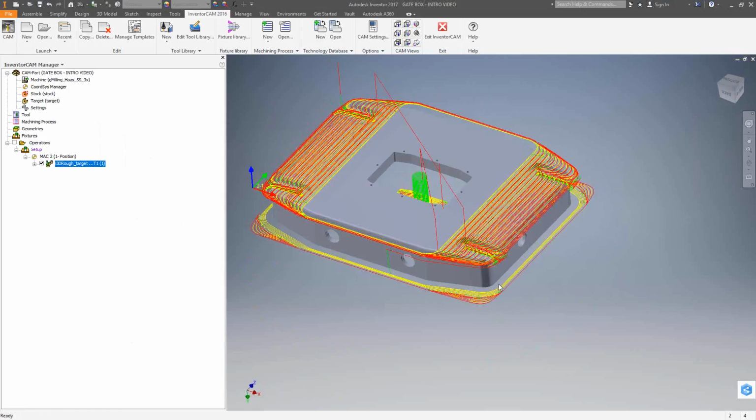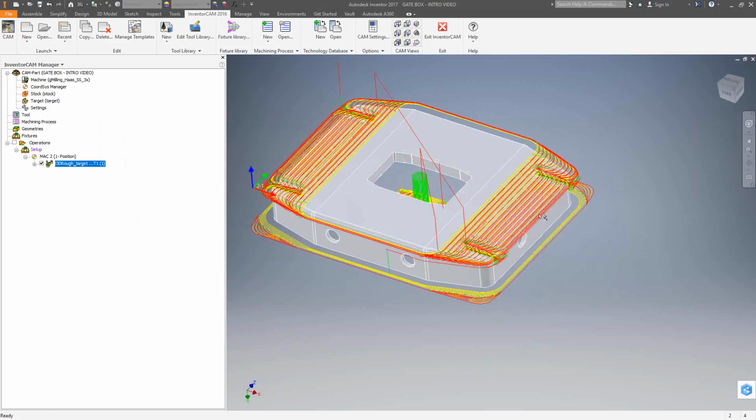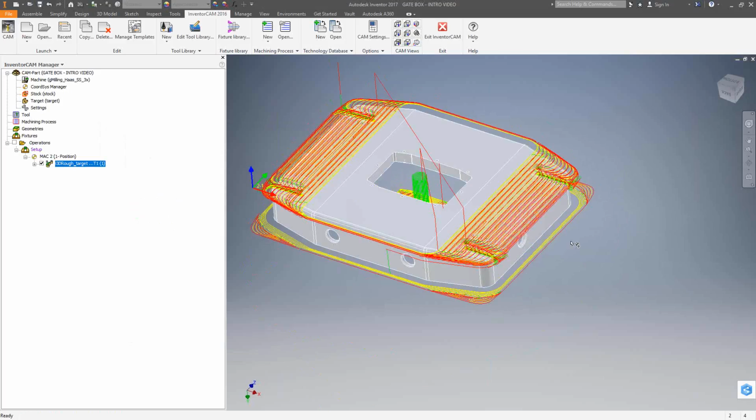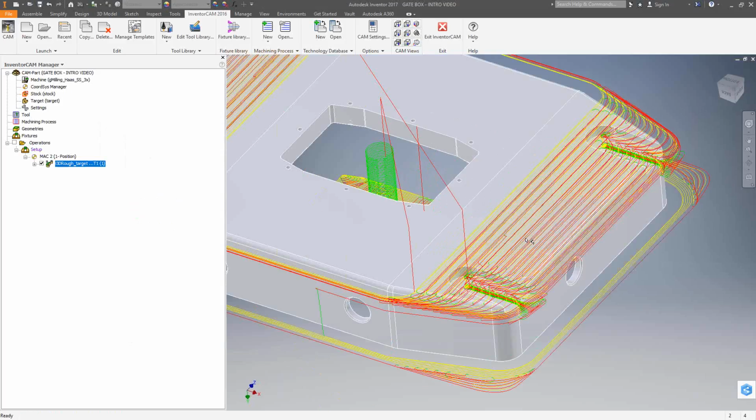Okay, so the toolpath began by machining off the excess on the corners, and then it worked its way up this angled face, and it also did that center pocket there again. So again, it's checking the target against the stock to see what material can be removed with this 1/2" end mill. And there's our scallop taking place on the side there.